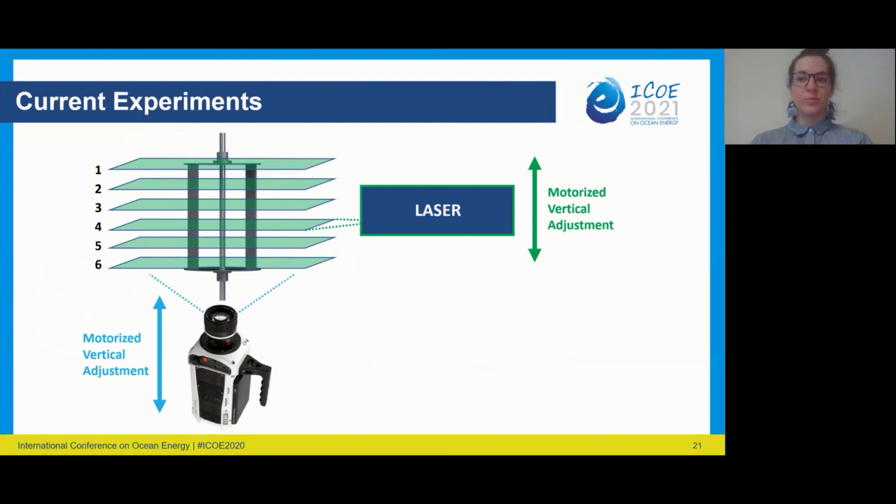So all of those results pertain to some experiments I did about 2 years ago, and were all taken at the turbine midplane. And this January, I was able to wrap up an experimental campaign where I took 6 different span-wise planes of PIV data. And this was made possible because I motorized both the laser table and the camera below the turbine, and so I could move them up and down to capture those 6 different planes.